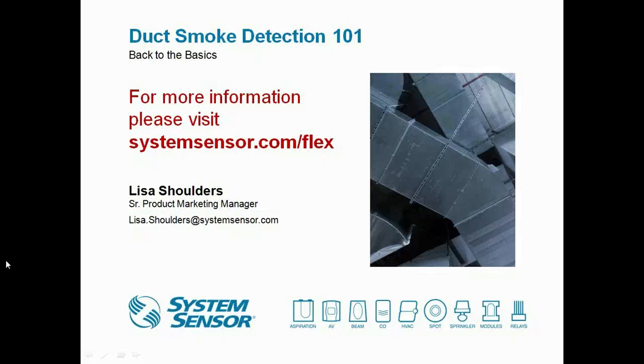Last question, was there a reason for angling the sampling tube downward 2 to 3 inches? Yes, there is a reason for doing that. The reason for having it angled down is, again, when I talked about mounting the duct detector on the bottom, angling the sampling tubes away from the detector just helps to ensure that there isn't an opportunity for water to accumulate in the housing.